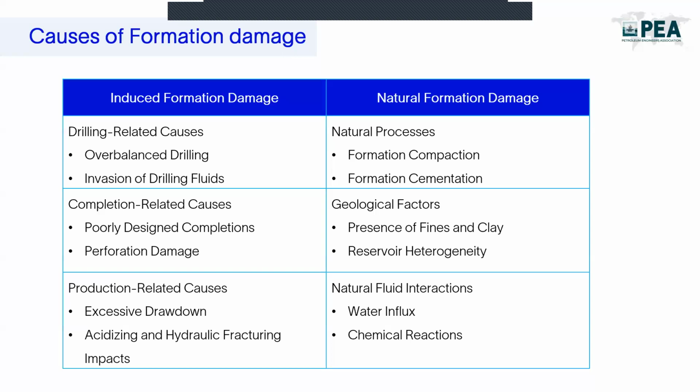For example, it's been said that if the hydrostatic pressure exceeds the formation pressure by 200 psi, we are more or less on the safe side. But as this difference gets bigger, we are expecting more invasion to happen, and we're expecting more reduction in permeability to occur.